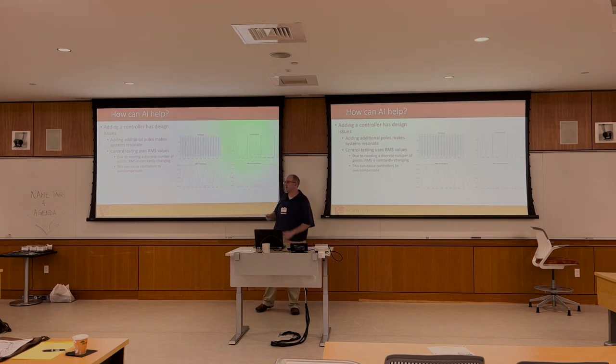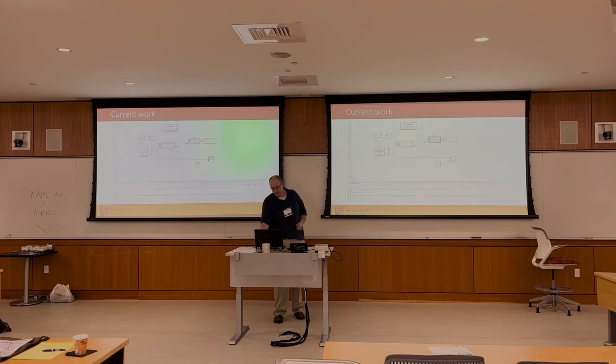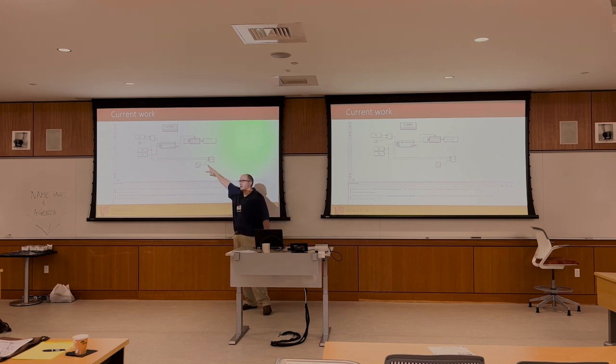Now, if it's low, it wants to say, okay, raise the amplitude. If it's high, it says lower. Fuzzy could help, I believe, with slowing that down because it smears it out, whereas the hard PID controllers are like, okay, do this, no matter what, do this. We don't want that to happen. Now, in current work, I'm starting to make the program for making these controllers in MATLAB. I'm having issues with it adjusting the frequency, but that's where I currently got to, which is why this is a nice looking control loop, because I'm just trying to get the team to change this sine wave that is being generated.